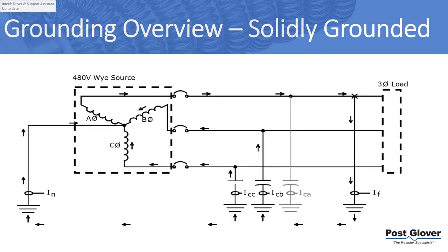So we think about ungrounded systems, we think about overvoltage problems. Solidly grounded systems is, I would call it, from a historical perspective, the answer to that. You see ungrounded systems being popular in a lot of manufacturing in the 30s and 40s. And then in the 50s, you start to see, probably because of these issues, the surging of solidly grounded systems.